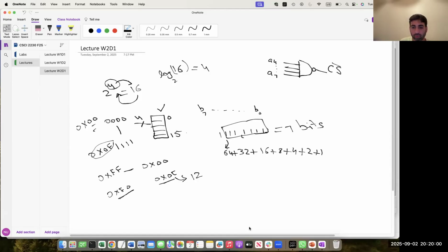Okay, thank you. He said 0x12. So let me write here 0x12. Now, in our example, is it in range or out of range? It is out of range because our memory can accept addresses only in the range 0x00 to 0x0f, right? So it means that for this address, the chip select signal should be equal to 1.